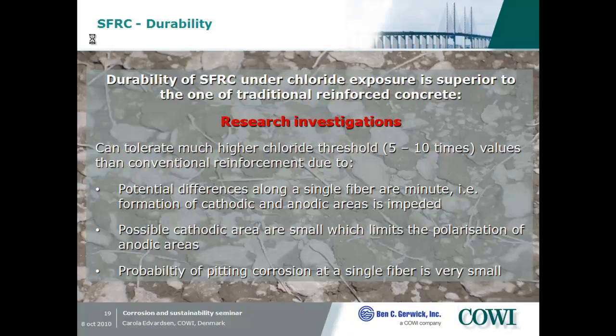The reason is that it can tolerate much higher chloride threshold values, up to 10 times higher. And there are some different reasons given here. The most important one, and Birk maybe can go on it later on if we have time, is that along a very small fiber the formation of a cathode and anode is almost impeded because we have only such a short fiber. So the probability of pitting corrosion is very, very small.